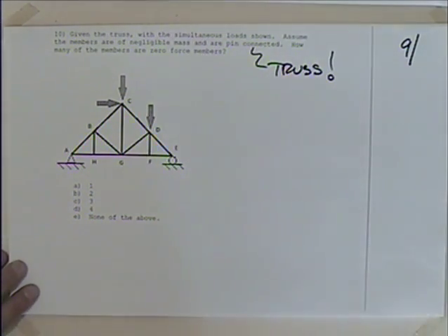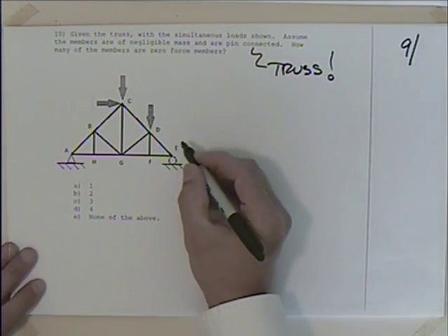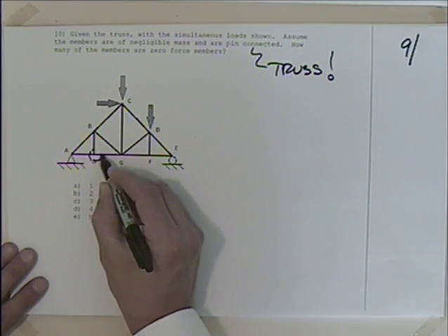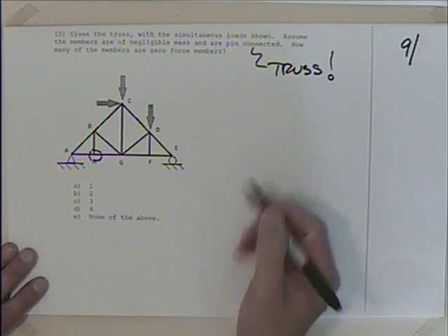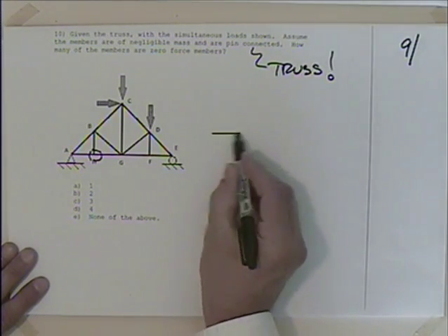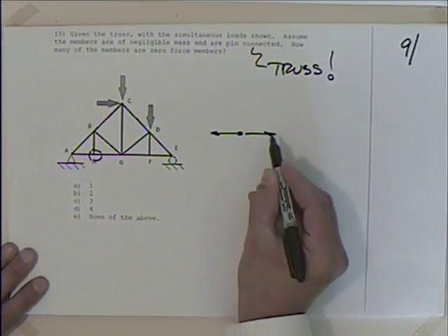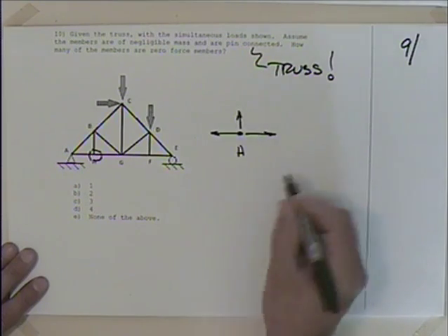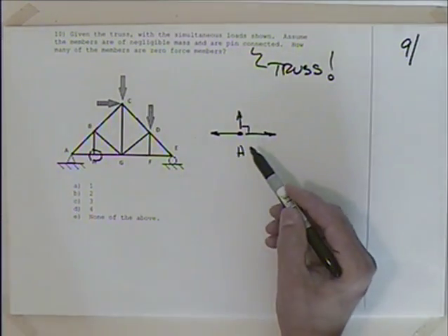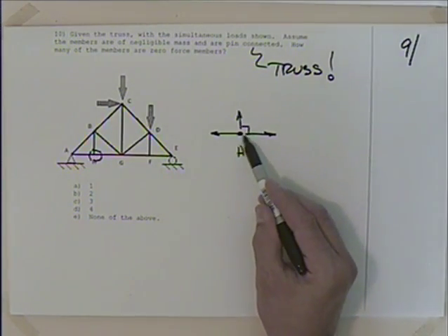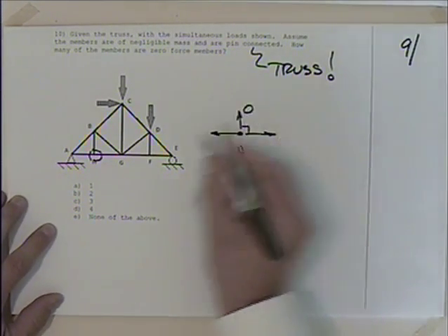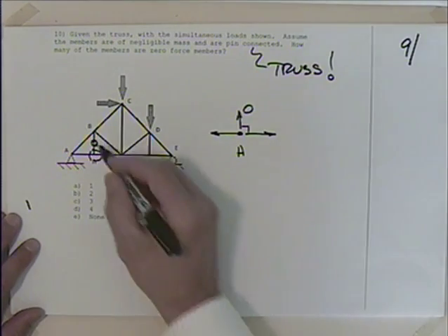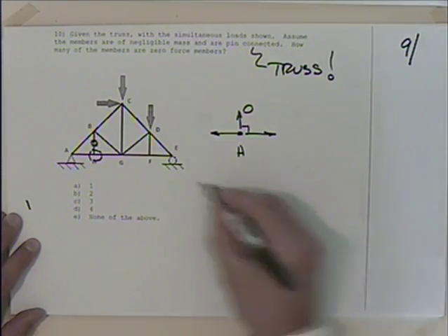I mean, if you wanted to, you could put some loads in there, but let's see if we can work our way through here. Typically, where you have an intersection like this can be a big deal. So if I do a free body diagram at that guy, I'd have something like this. And something like this. This is point H, and then something like that. That's at right angles. Even if it weren't at right angles, I have no other loads, so I know this has to be 0. Okay, so that's a zero force member, so let's keep tally. There's one of them.